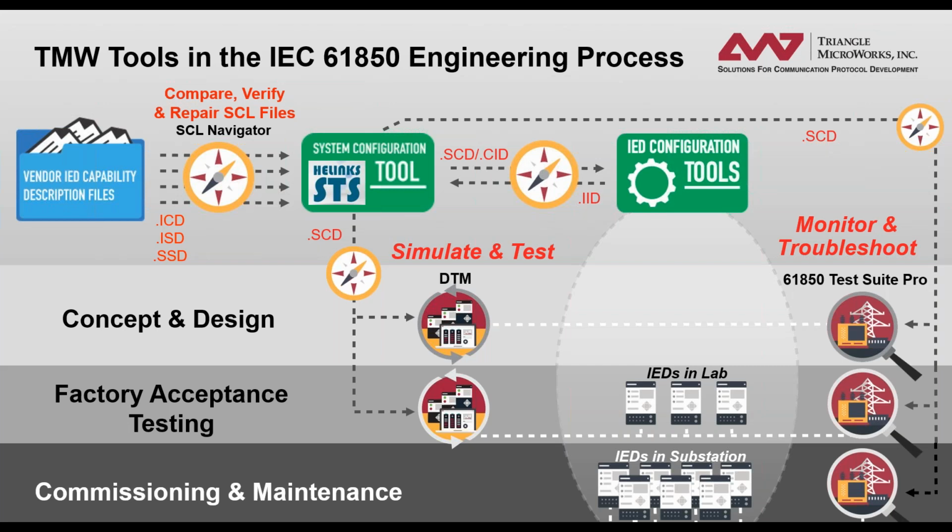The IED model revision, okay, if you change the IED model, there is another information, which is the revision of the model. That's, of course, when you import an IED with an updated model, you need to consider that as well. Doesn't necessarily require that you every time recreate everything, but if you have a model change in the IED, then apparently you did it because you need these additional signals. I'm not sure if the config revision was referring to those.